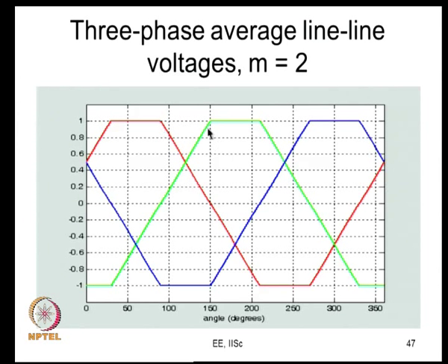And if you take this region for example, or take this region, what is this? This is VBR. VB the lower device is always on and R phase the top device is always on. And similarly you look at here, VYB is VDC. So, Y phase top device is always on and B phase bottom device is always on during this now. So, you can see that they have started switching lower and lower. So, actually for R phase, any particular phase, for 120 degree it does not switch, it switches only during those 60 degrees around the 0 crossings, the first 30 degree and the last 30 degree in every half cycle.